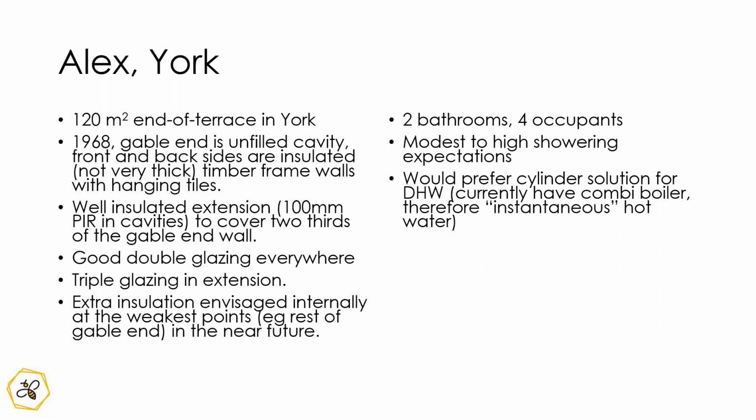Yeah. And the other thing though is that again, as in the last case, you need a proper survey for the heat loss, so you know what your heat loss is. And I should imagine, with what you're saying about the insulation you've got and you're putting in, that you probably get your heat loss down to somewhere where you could use a 5 kilowatt heat pump.